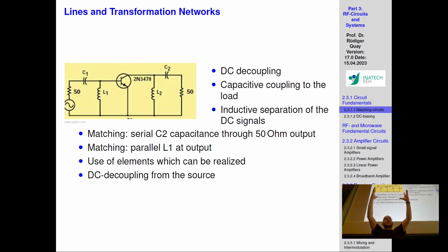You're having these two-port devices, and you want them to be put sequentially next to each other. So you have a two-port device, another two-port device, and another two-port device, and this has 5 dB gain, this has 5 dB gain, this has 10 dB gain, and in the end you want to design something that has 20 dB gain. So you put them next to each other. The signal comes in here, gets 5 dB amplified, comes in here, gets 5 dB amplified, comes in here, gets 10 dB amplified. In the end, when you look from the output to the input, you have a signal that came in at 0 dB and a signal that came out at 20 dB. So you have 20 dB amplification across the device.